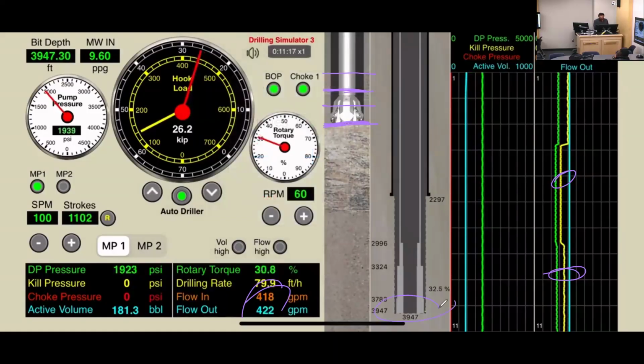Look at the yellow spots here. They are going to get bigger and bigger because now look, I get 432 out, I only put in 418, so I am in trouble. Also, my ROP increased here at the bottom. I'm ignoring it. I'm young, I haven't noticed it. Somebody's telling jokes on the rig floor. And the kick gets bigger and bigger.